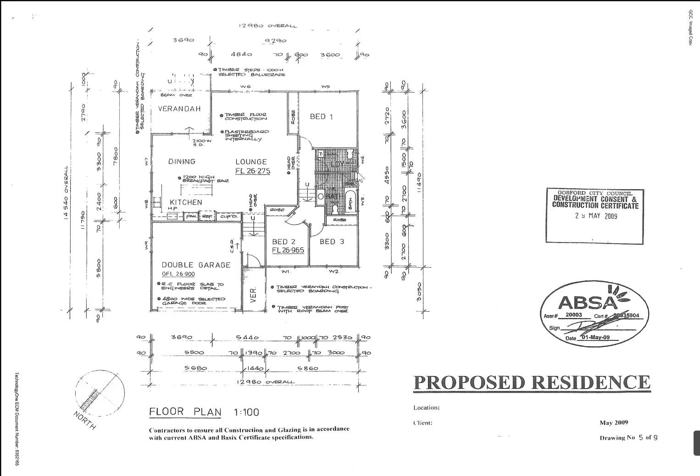Okay, here we have an internal wall at this position. Then we've got a shower, SHWR, I think that says. I can't really read it. We've got a bath, another toilet, a vanity unit. So a vanity unit is just your basin in there. And they're all actually shown at the same floor level as the main lounge room here. So that's all at one level. Then we go up a couple of steps into the 2 bedrooms at the front of the house. And you'll notice that they are 65 millimetres above the garage floor.